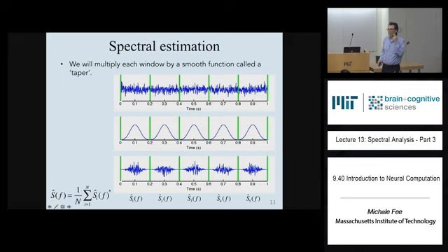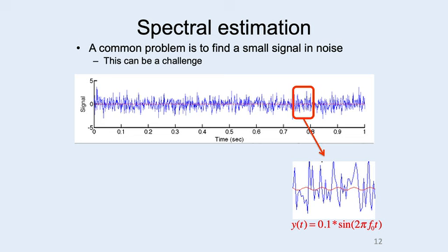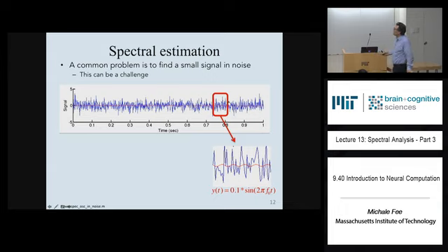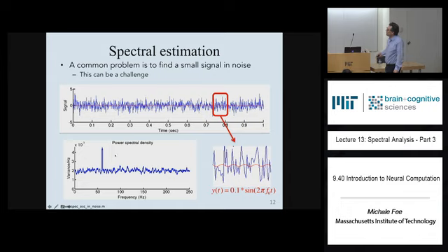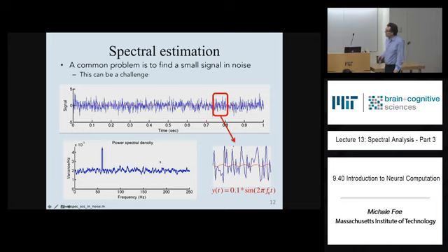Any questions? Okay, again, that was the review. And I showed you briefly what happens if we take a little piece of signal. The blue is white noise with a little bit of periodic sine function added to it. If you run that analysis, you can see that there is a large component of the spectrum that's due to the white noise. That's this broadband component here. And that sinusoidal component gives you this peak. And I've posted, or Daniel's posted, a function called wspec.m that implements this spectral estimate.